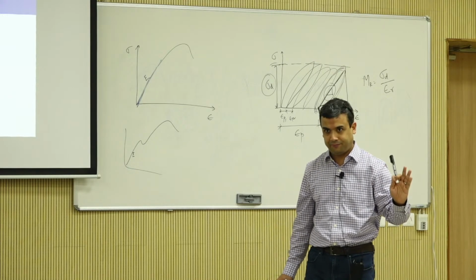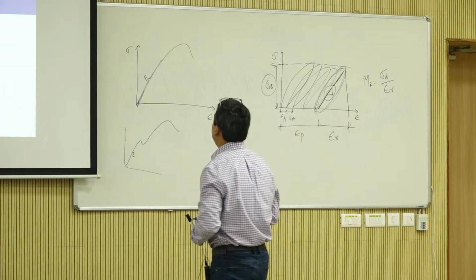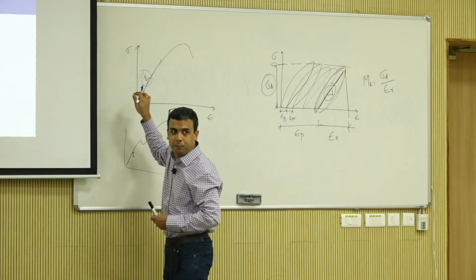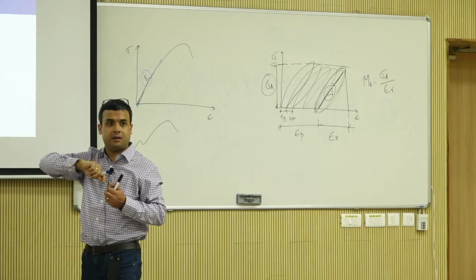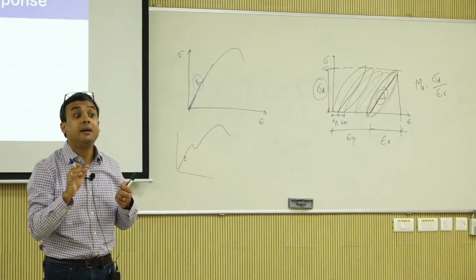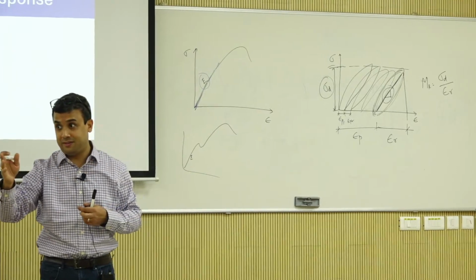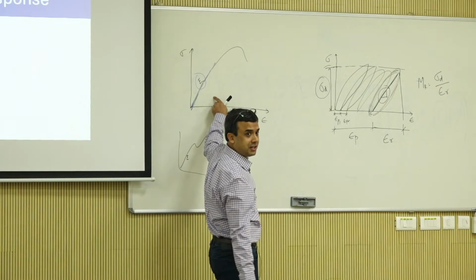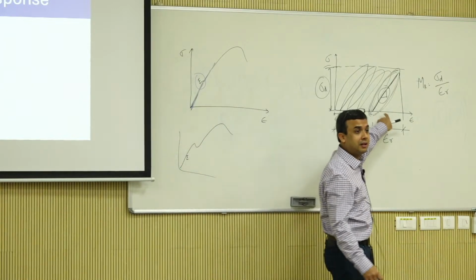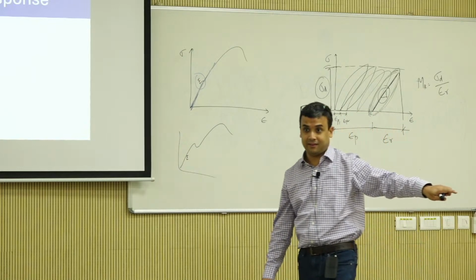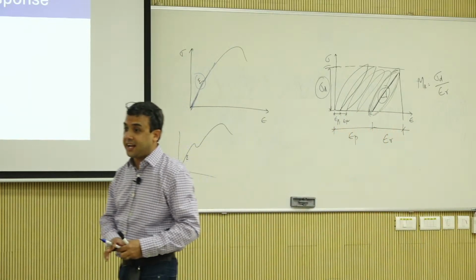Now let's go back to the definition of modulus. What kind of a modulus is it? The hint is mathematics, like graph theory. Tangent modulus. It's a tangential modulus; you're drawing a tangent to the stress strain curve. What are you drawing here? It's a secant modulus, right? So it's a secant modulus.